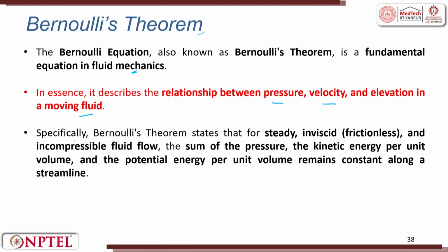Specifically, Bernoulli's theorem states that for a steady, inviscid, which is frictionless, and incompressible fluid flow, the sum of the pressure, the kinetic energy per unit volume and the potential energy per unit volume remains constant along a streamline. We saw what are streamlines.